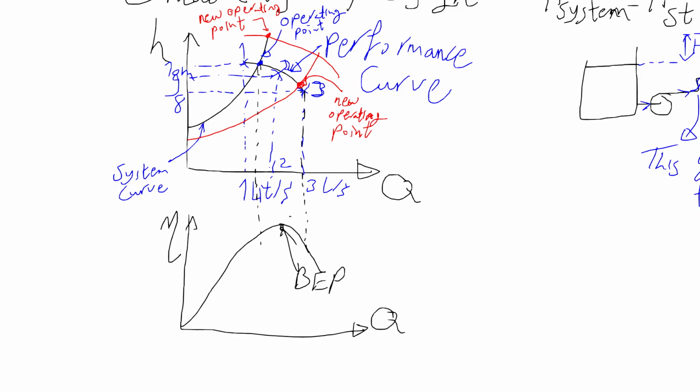For positive displacement pumps, life is much simpler. These pumps deliver almost the exact flow rate you select, almost independent of the pressure. But that comes with a responsibility. You must ensure that the pump and the system can withstand the pressure generated. If you choose a pump that can produce extremely high pressure for a low pressure system, you will simply waste money. And you might even damage the system if protections are not installed.